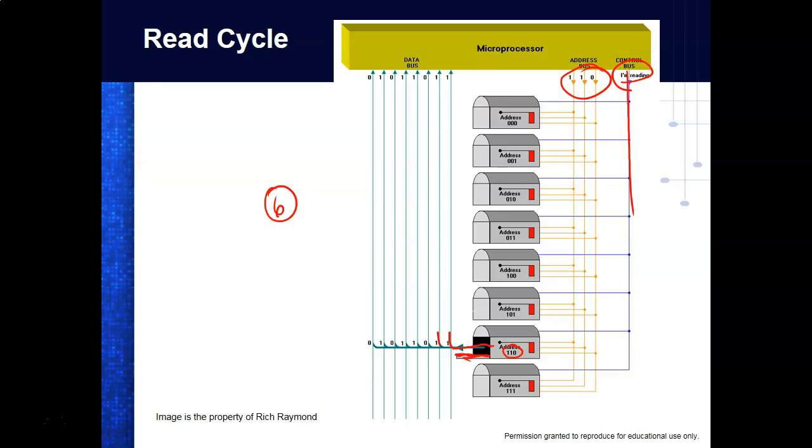So we looked at two basic cycles, a read cycle and a write cycle, but you got to understand, we have a 16-bit address bus, so that's 65,536 addresses this guy could put out, just for I/O. So we're still dealing with a 16-bit I/O address bus that selects input output. That's 65,536 ports I could have out there. But we got to tell these devices what we're doing. So the address opens up the mailbox. The control bus tells the mailbox what I want to do, and the data bus is where the information is actually exchanged between the device and the microprocessor.